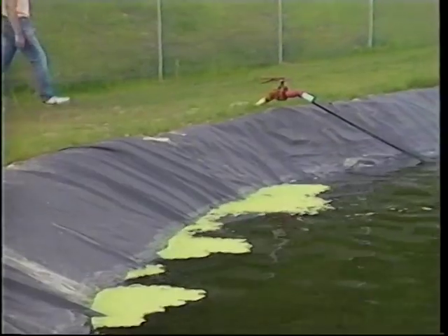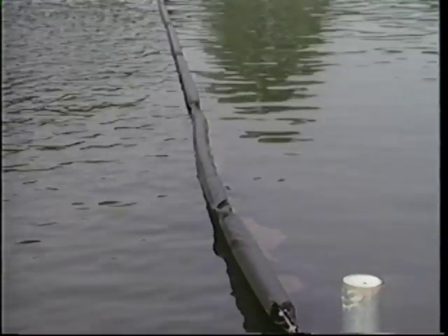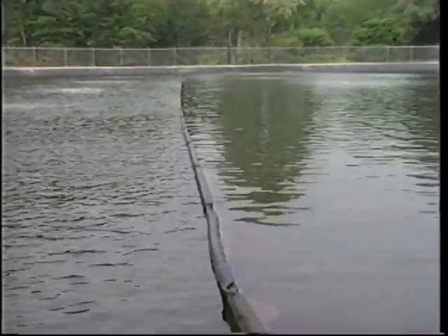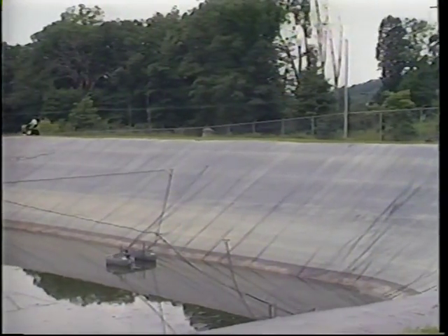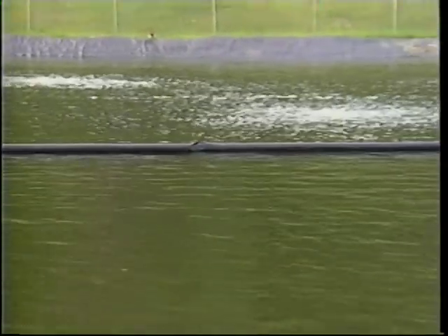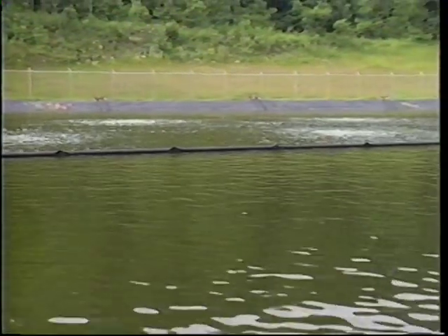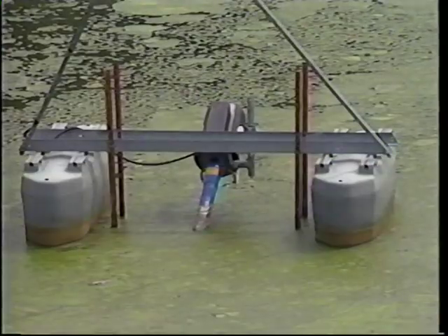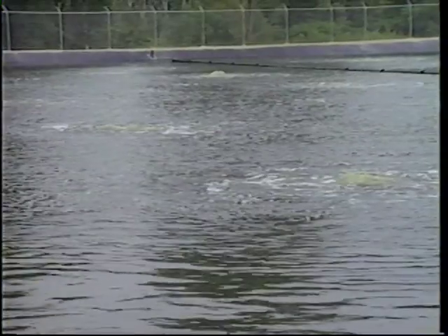The lagoon depth is dependent on the design of the system. Lagoons may be operated in series of 2 or more and may be baffled accordingly. Some lagoons are built only for storage or flow equalization. Detention times of lagoons vary depending on design. A lagoon that has a detention time of 3 days or less will have little or no biodegradation of waste material. In lagoons that are aerated, you may find surface mechanical aerators or subsurface diffused air systems.